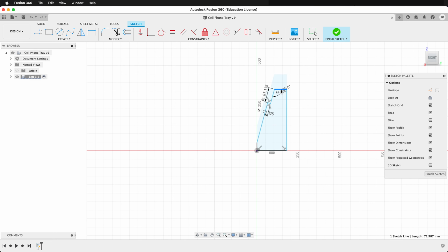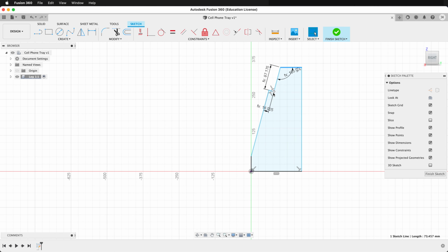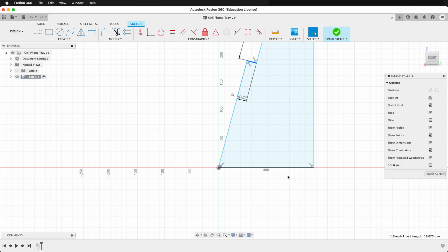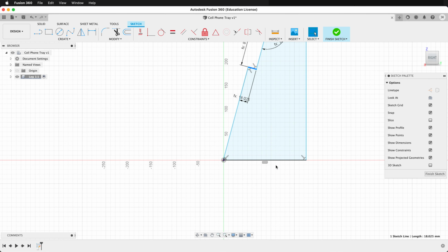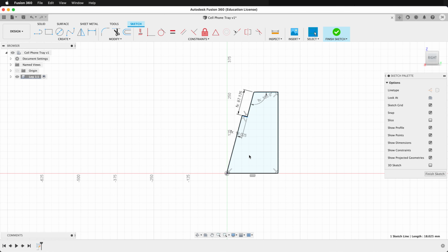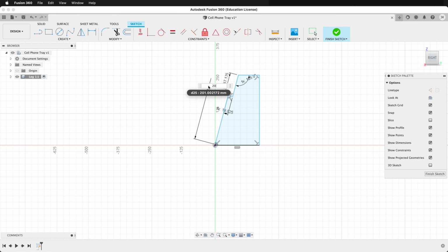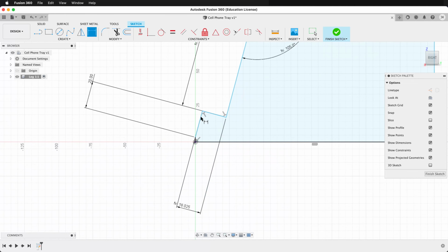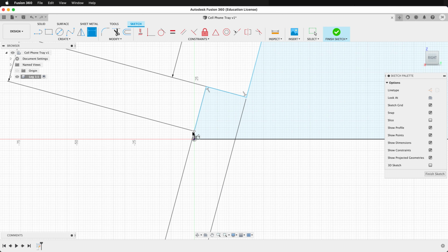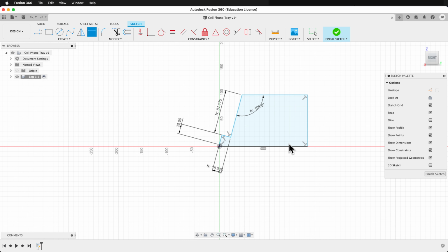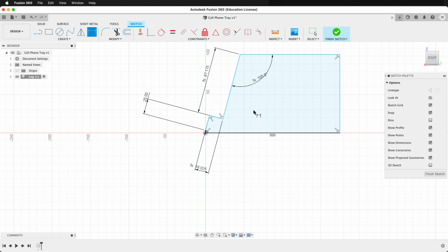What we need to do is really just bring this whole thing down, and then we'll change the dimensions of our sketch here. So for example, this line here is super wide, but we'll fix that. So first, we're going to go ahead and give this line a dimension of 20. That'll pull the sketch all down and be closer to the size that we want. Now this is the strange dimension that's super long. So we can go ahead and fix that by drawing in our legs. So we want to have some legs to this. So we're going to draw an angle like this.